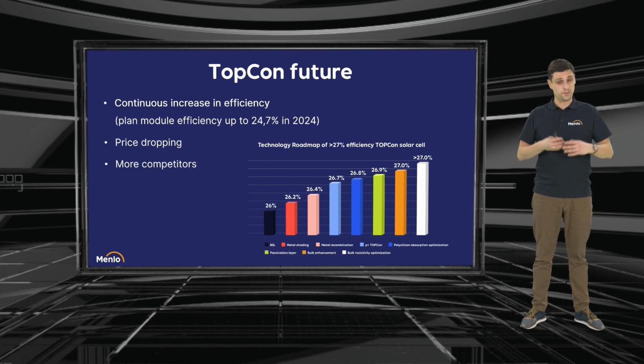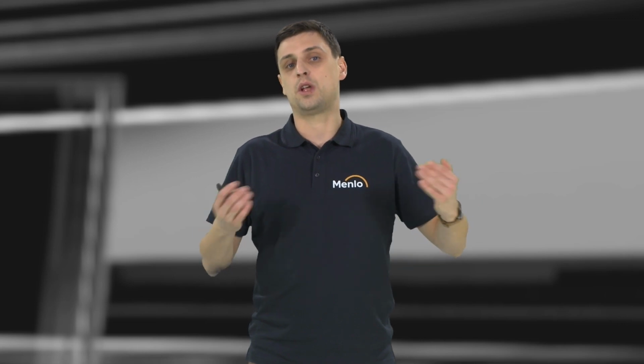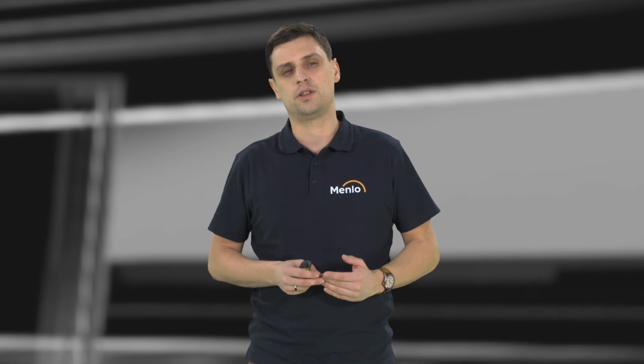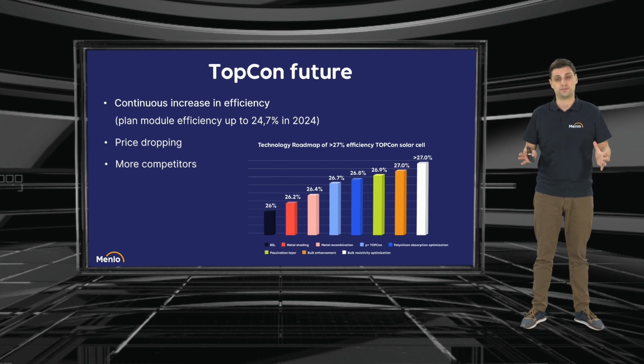What does it mean for you, for an installer? Models with 108 cells, the most typical domestic models in P-type technology, reach power of like 410, 415 watts today. N-types in the same size of frame, on the same surface, already reach 435. If those predictions are valid, next year we will have a 490 watt model with the same size. So that's the future of TopCon, the most developed technology right now.